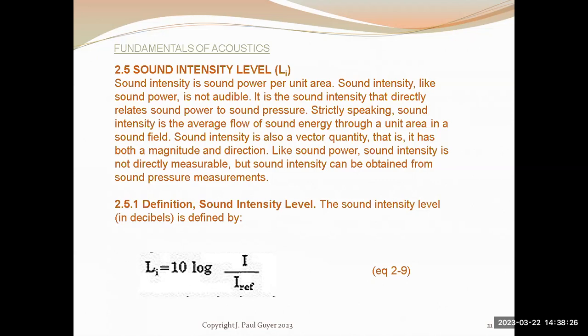The sound waves, if you will, are impinging on a wall between a source room and a receiving room. And the sound intensity is the sound power per unit area of whatever area you are dealing with, the area of a wall between two rooms, as an example.